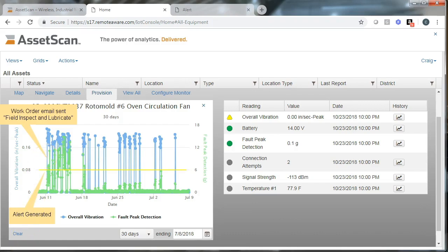In our case, we generated this prescriptive task in an email to the production superintendent. He sent that email into his work order system, worked through their backlog, which is typically about 10 days. And as you see, 7 days later, completed the work. And you see the Gs in that green line reduced from 10 or 12 Gs to 2 to 3 Gs, well underneath the 6G limit.